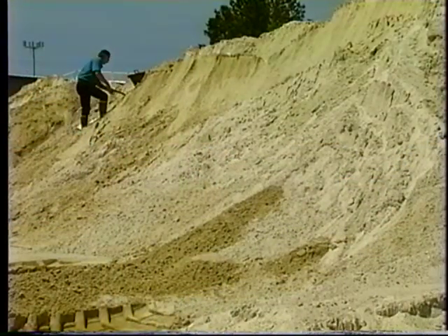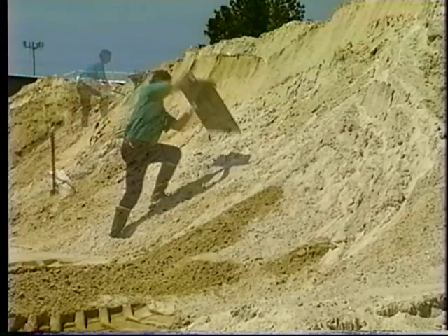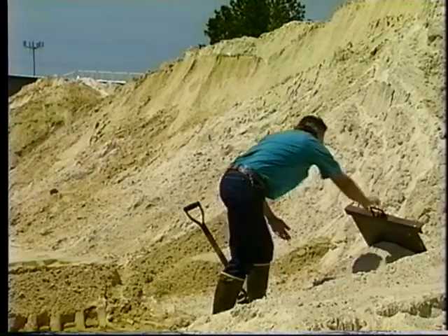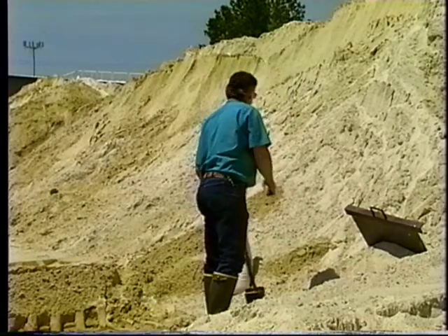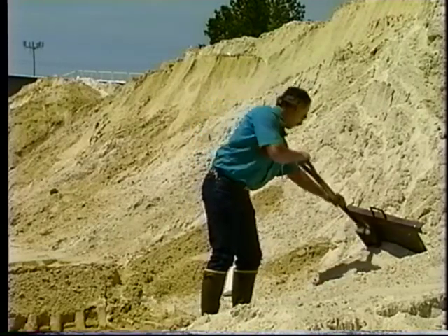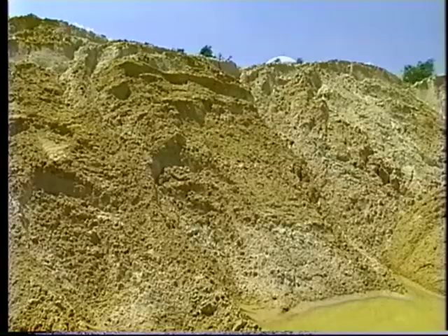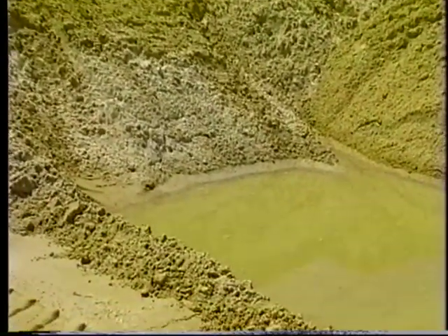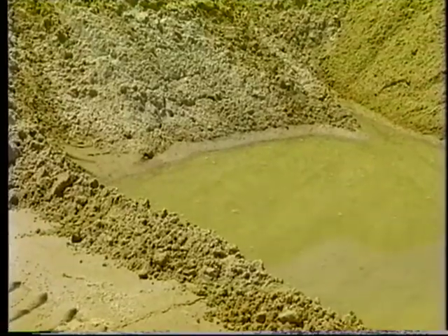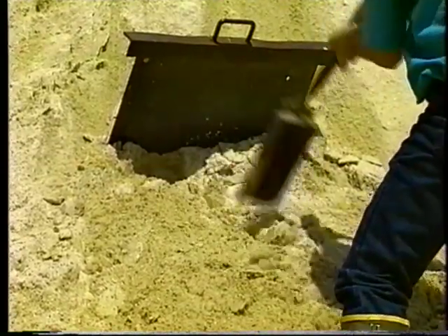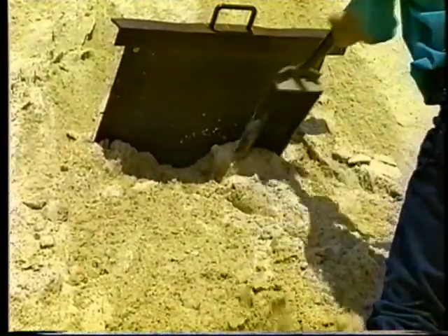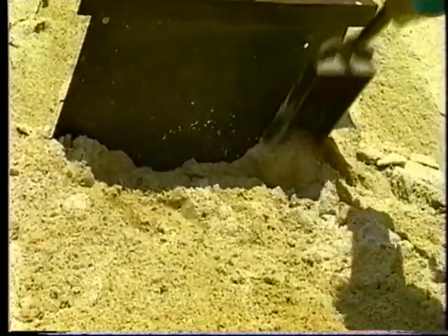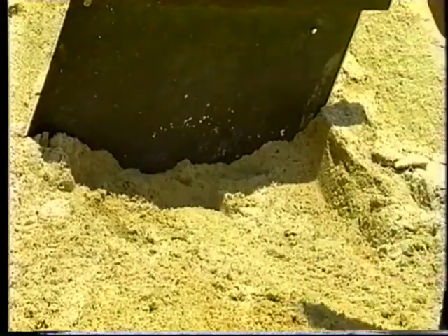Take composite samples by obtaining material from 3 different levels of the stockpile: near the top, the middle, and the bottom. Be careful not to contaminate the sample. Avoid sampling from the base of the stockpile, where samples may be mixed with ground soils or contain excess moisture. When sampling at different levels, avoid sampling one area directly above another. This prevents material rolling into the lower sampling area, which is a source of segregation.